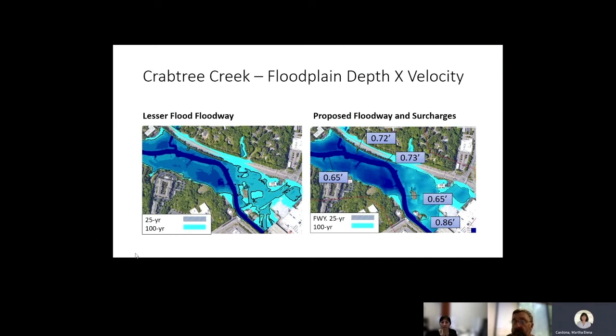Yes. So the conclusions. First conclusion is my friends have been telling me a D times V of 1 is appropriate. They've been lying to me, or at least what I'm seeing is that some of my friends have been lying to me. Maybe values of 5 to 7 are more appropriate, but that's probably only for typical floodplains